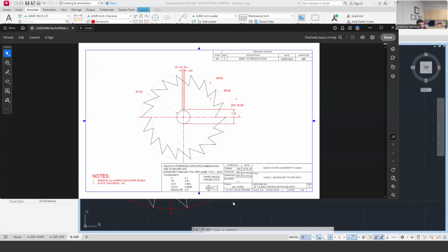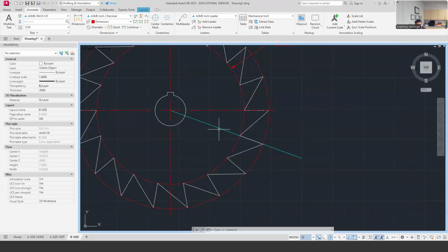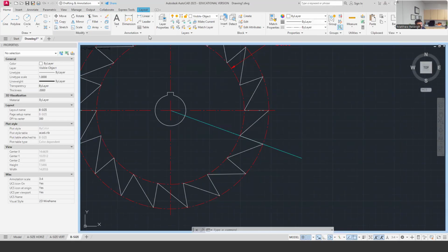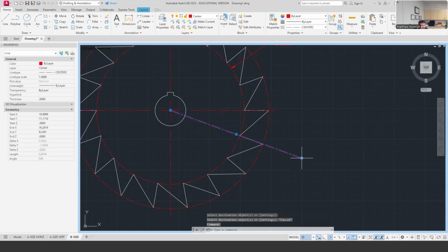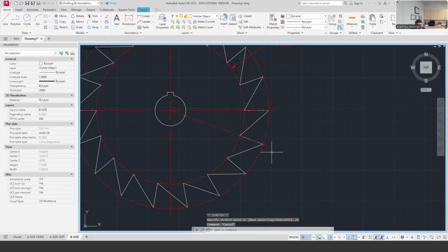And then I'm going to dimension, so I'll put my 18 by 20 degrees on the one that I have already as a construction line. So I'm going to turn that into a center line, and I'm just going to match properties there. Then I'll do the ASME rule here. So I'll pull this out, make sure I don't pull it off of the right angle, but just a 1/4 inch extension past like this.